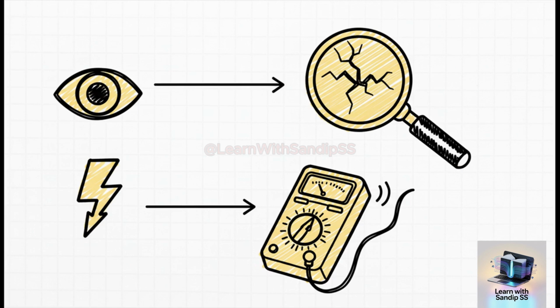So for that visual inspection operation, a characteristic might be check for superficial damage. And for the functional test operation, it might be measure power consumption. You can even specify the exact inspection method or the piece of test equipment to use. See what we did? We've gone from the big picture all the way down to the finest detail.